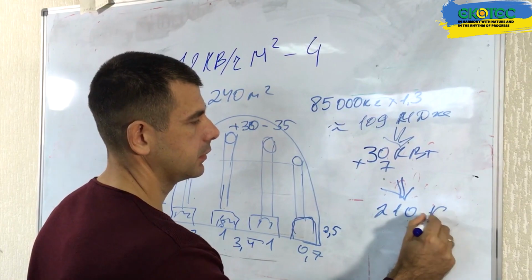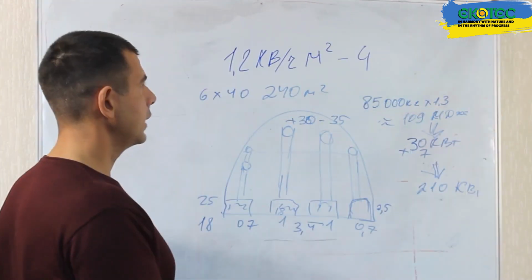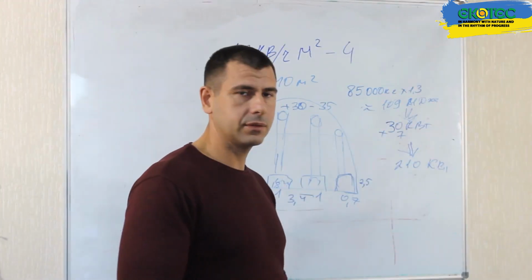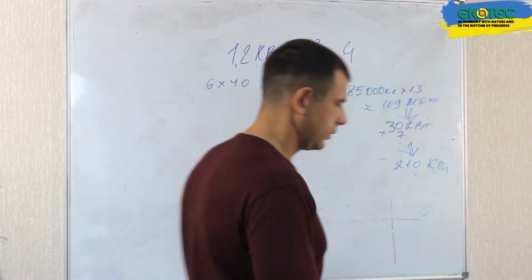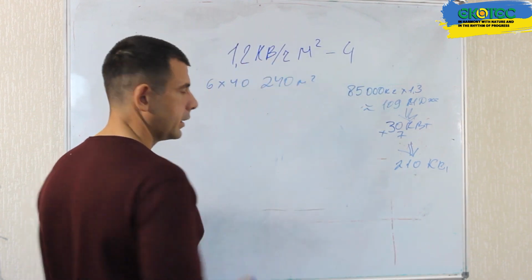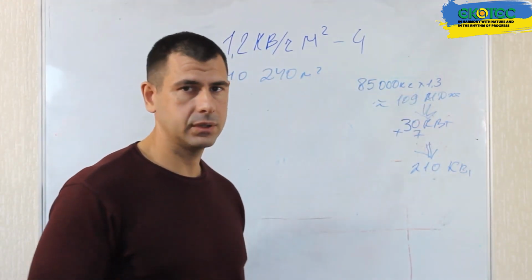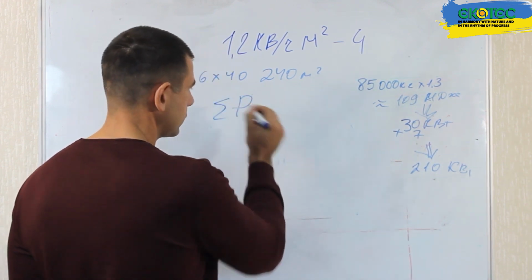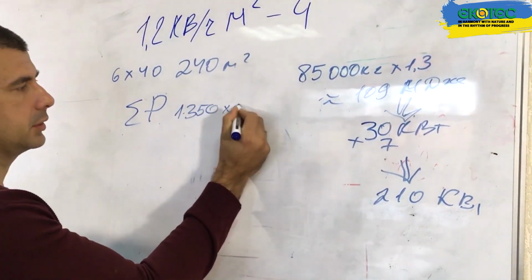Since we have a temperature of 35 degrees Celsius at the top and 18 degrees Celsius at the bottom, let's assume that we capture very conservatively, only 7 degrees. The heat we capture is 4,800 multiplied by 7 degrees, multiplied by 1.185, and multiplied by 1. Here 7 degrees is the change in temperature that we capture, 1.185 is the density of air, and 1 is the heat capacity of air. As a result, we get the figure of 11 kilowatts per hour, which is what we accumulate in the ground. That is the minimum that we can capture in the winter period.